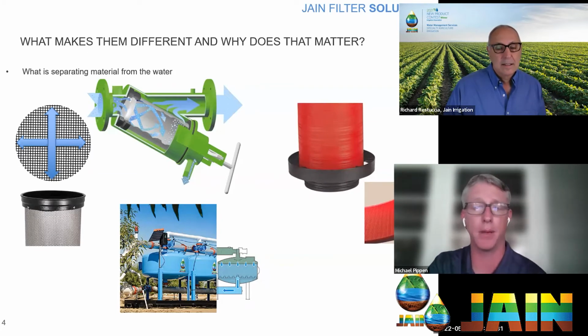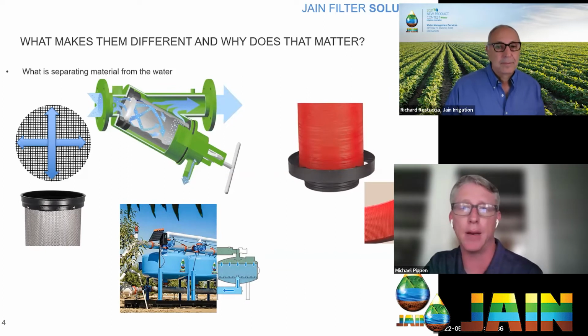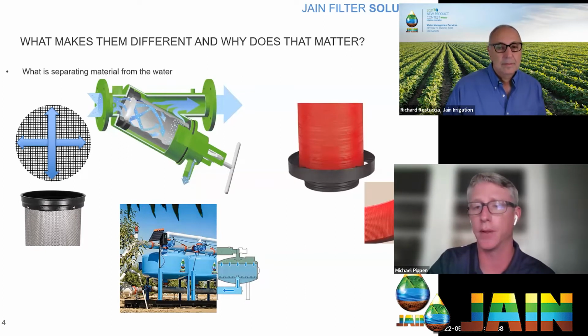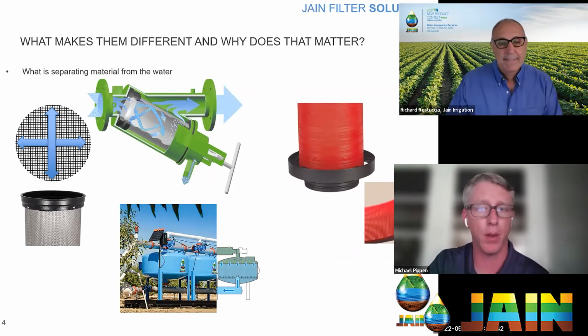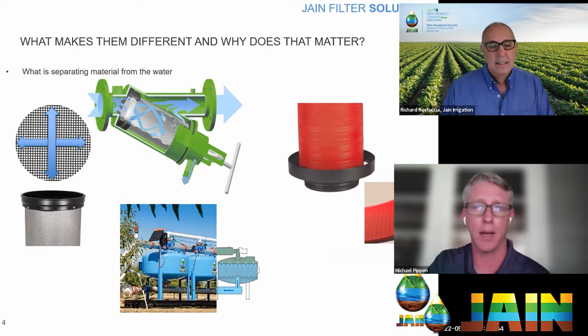We sell a lot of them and put up a lot in operation in the Southeast, where we're using a micro jet or a micro sprinkler where the filtration requirement isn't quite so much. We're coming off of wells, don't have a whole lot of organic materials in there. We have a lot of high volumes and relatively low amounts of sediment in the water. They work extremely well in that kind of application.